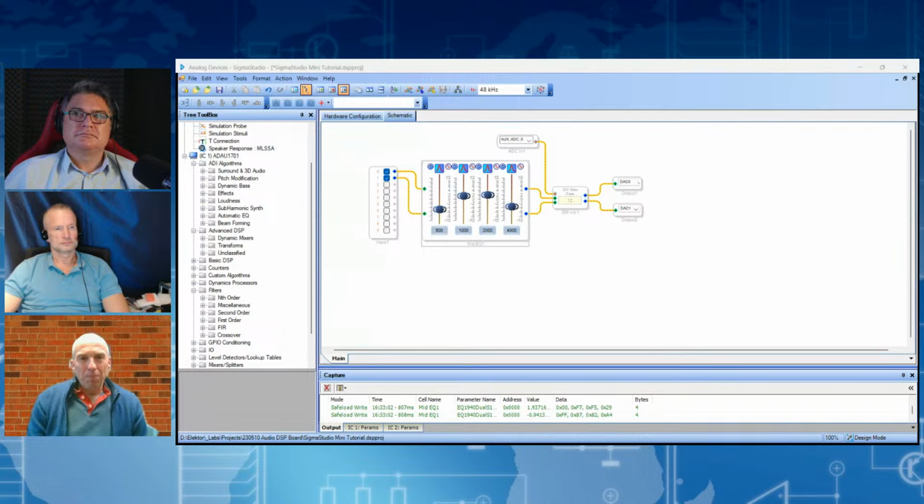But there is another way. There are people who have reverse engineered parts of the DSP algorithms. And so you can also control certain parameters over I2C. And you could do that with MIDI as well. So you convert MIDI to I2C, and then you can control some parameters of the DSP. So that's very flexible. Those options are available. You can also go the other way around if you like, and in theory, use the potentiometers to send MIDI data to something else. So you can also use it as a MIDI generator. Awesome.